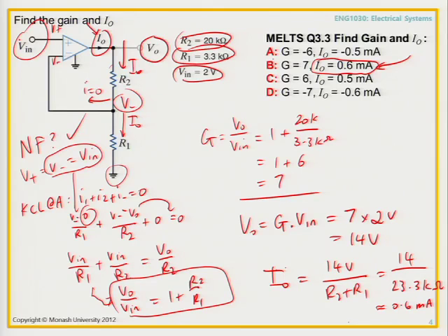Okay, so that's the takeaway message here. Any current that you see when you're working out with op amps is really coming into or out of this output terminal. And in addition to that, that current is really coming either from the supply terminals. So you've got that VS plus here and the VS minus here, those two supply terminals.